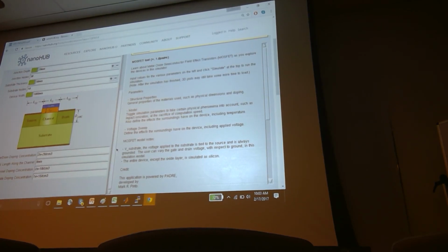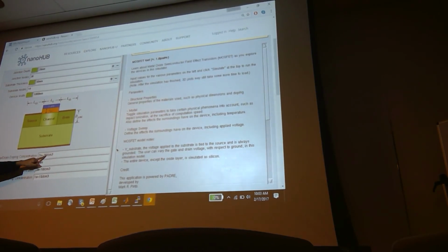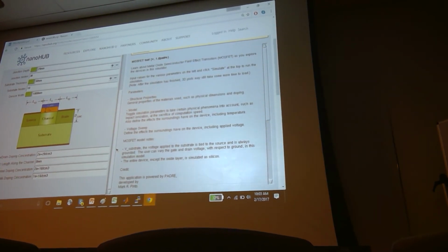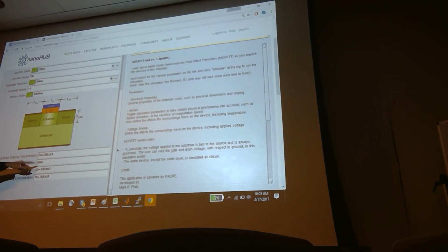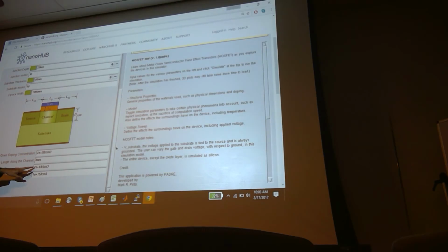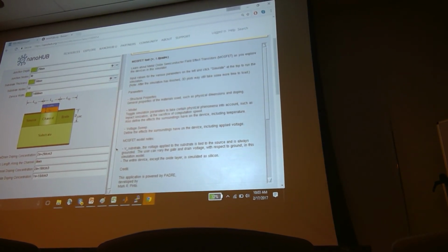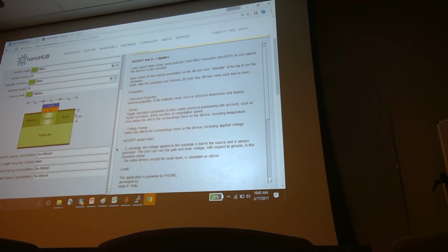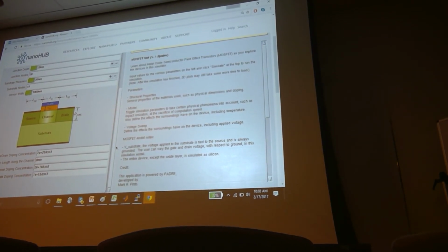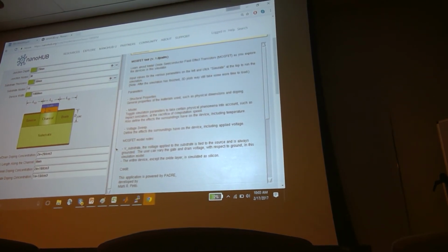And if you go down, you can also set your doping. So you have the peak source drain doping. It's usually very high because you want it degenerately doped. And then your channel doping, you need to calculate this, and you can check using this simulation that your threshold is right. Now, I suggest using the software because this is the only way you can prove that you're actually right. So when you do the presentation, you can show the simulation and say, yes, I was right. Even though we cannot check your simulation and know whether you're right or wrong, you can at least justify.